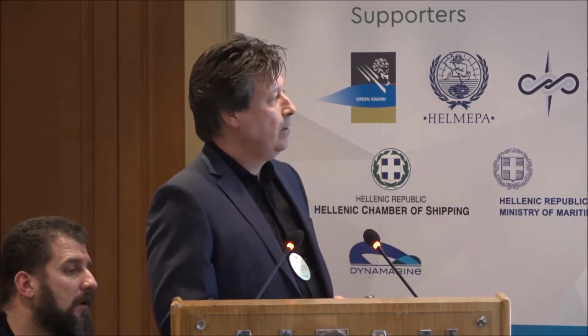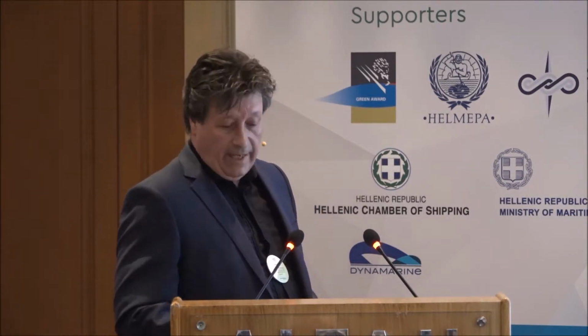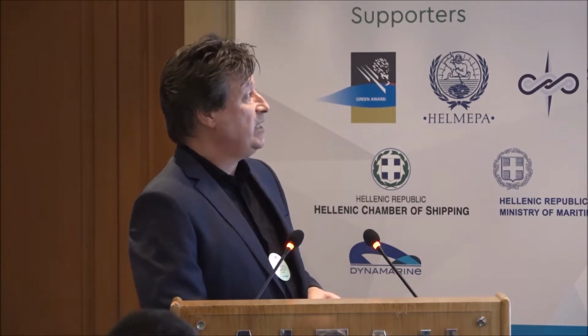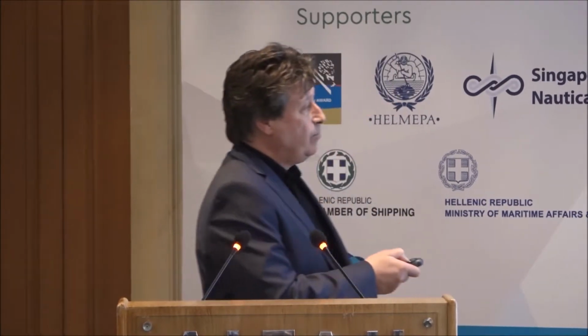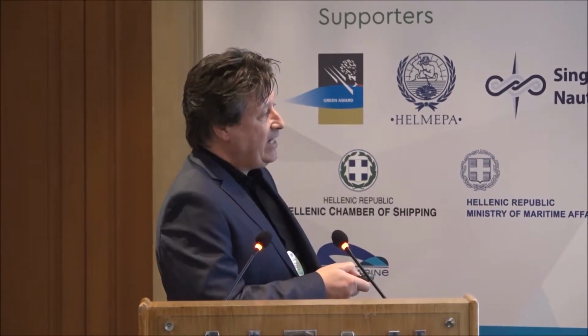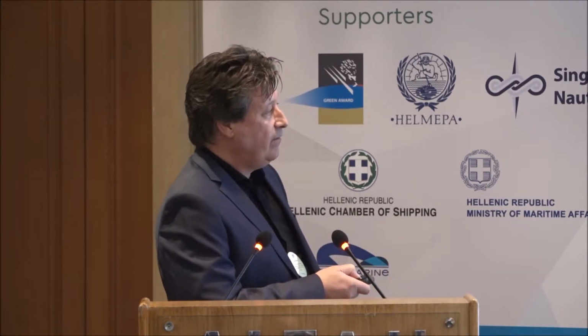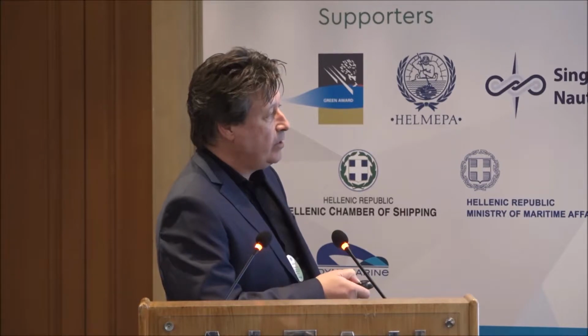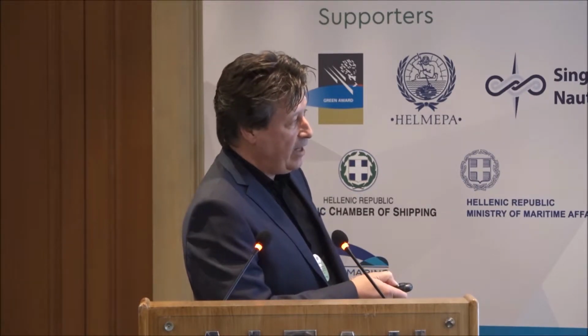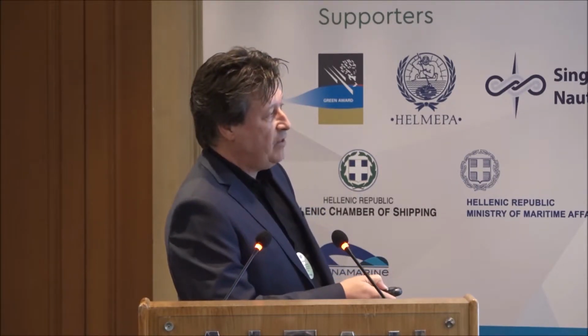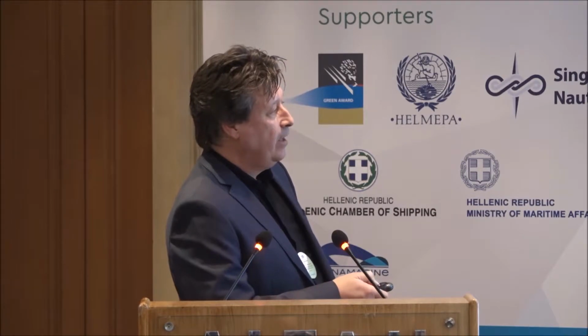Right. So that was the berth window. Here's vessel data. So this is host vessel. So basic dimensions: length, breadth, width, the X, Y, Z position of the target. So for gas, vapor manifold, center of the vapor manifold on both sides. You select the current drag coefficient data set here, the wind drag coefficient, the hydrodynamic coefficient files for waves.